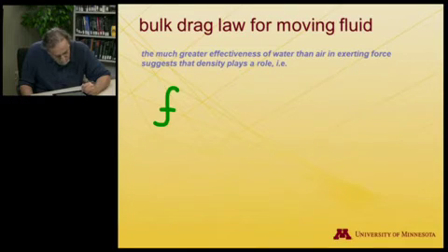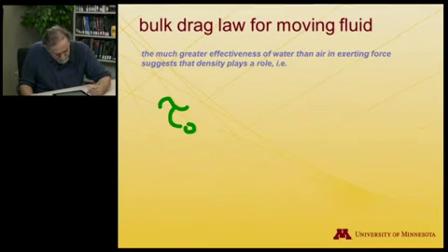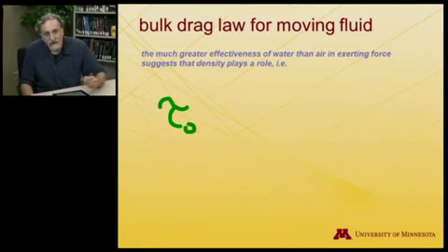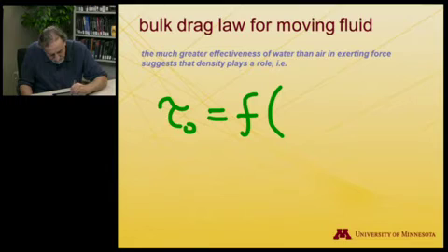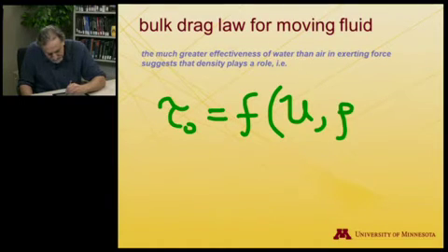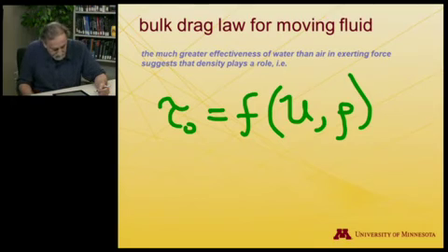So if we just take that experience and say, okay, common sense tells me that the force that water exerts should have something to do with the speed that it's moving, but it also should have something to do with its density. And I shouldn't say water, any fluid, any moving fluid. We could write a sort of crude equation that would say that the shear stress, so the force per unit area, and I'm writing it as shear stress on the bed, so we're switching our focus from forces on us to forces on the bed, but they scale the same way, can be written as a function of the velocity, we've already said that, and also of the density of the fluid, which we conventionally write as rho.